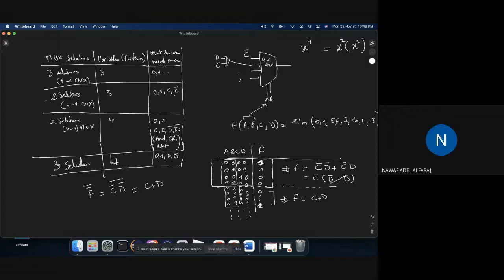What is a single inverter in chapter 3, slide number 55? Here you have just one variable that is inverted. I'm talking about the example on chapter 3, slide number 55. It says: implement F, given by its minterms, with an 8 to 1 line multiplexer and a single inverter. Yes, this is the inverter; it is used to produce this C bar.